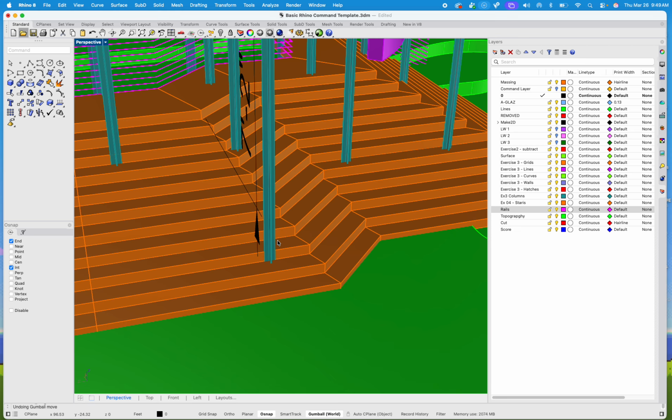That's a good question. No, right? So there is such a thing. That stuff can be so thin. I would not cut vertical dowels or any horizontal with the laser cutter. It's just gonna fly straight through it, and it's honestly gonna warp the piece a little bit. You might as well just get some dowels that are specifically the size that you need. That's honestly the easiest way.